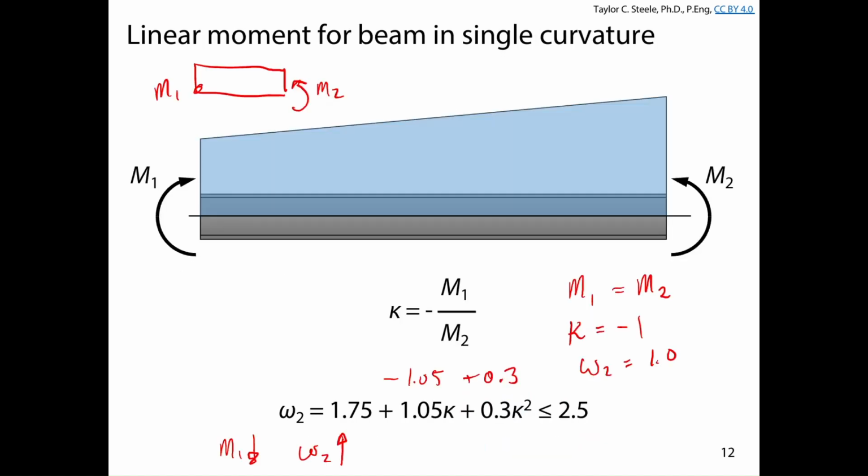So that's kind of interesting, and basically what's going on here is if the bending moment diagram is uniform, then the compression in the flange for a uniform bending moment is going to be the same. It's going to be equal compression from one side of the flange to the other. If the top flange is fully under compression, then it's more likely to experience lateral torsional buckling.